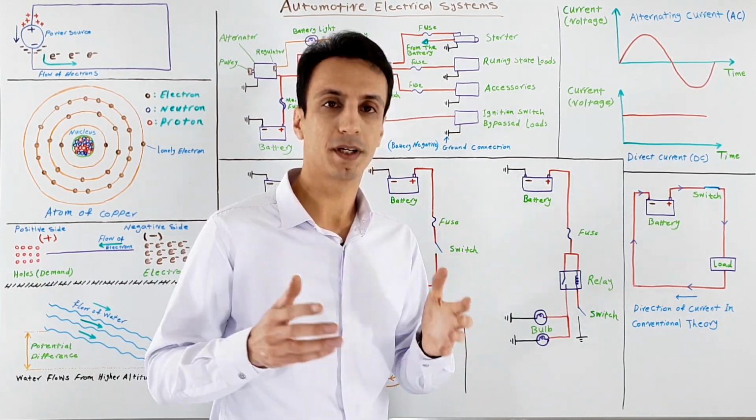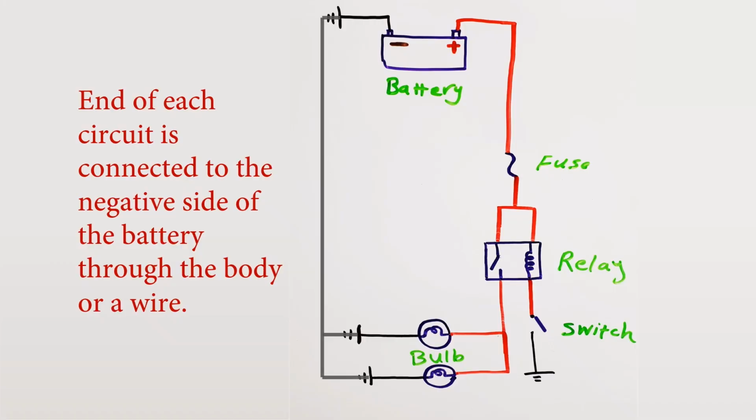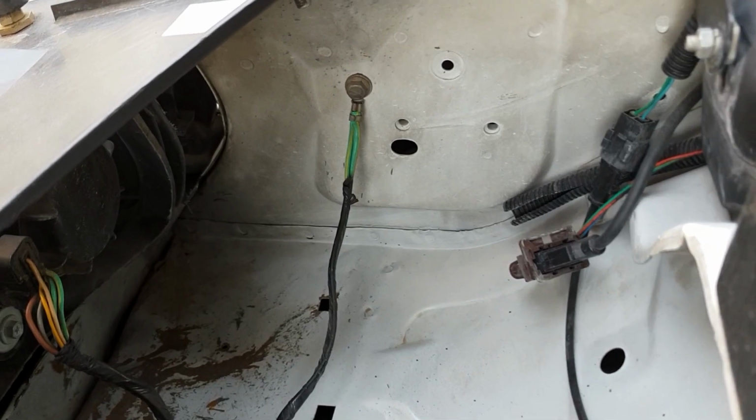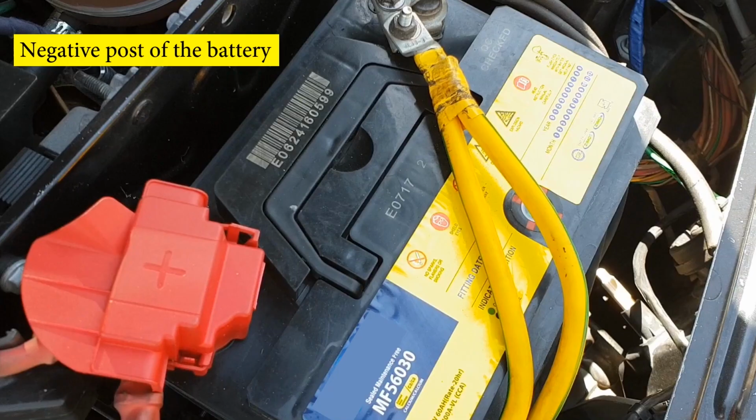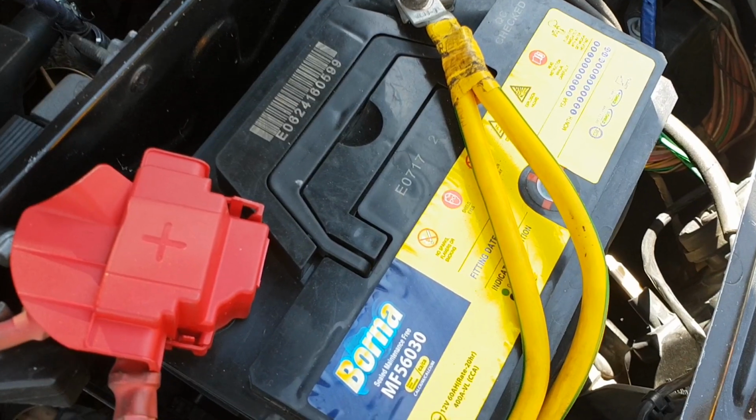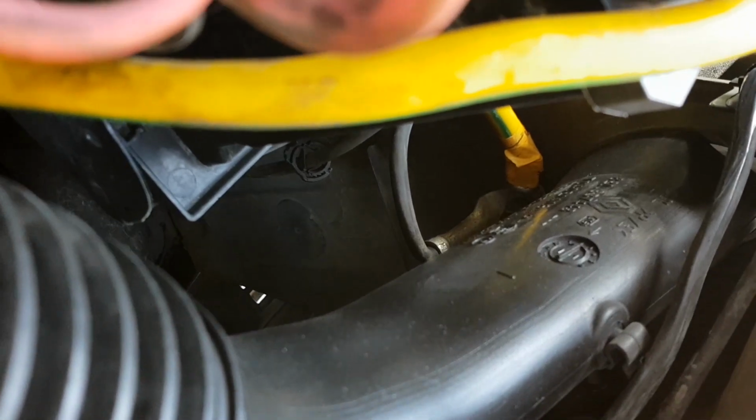So when we want to connect the end of each circuit to the negative or ground, we don't need to connect that directly to the negative post of the battery, and just connecting that to the bare metals of the body is enough. This ground connection is done by connecting ground straps between the battery and the body.